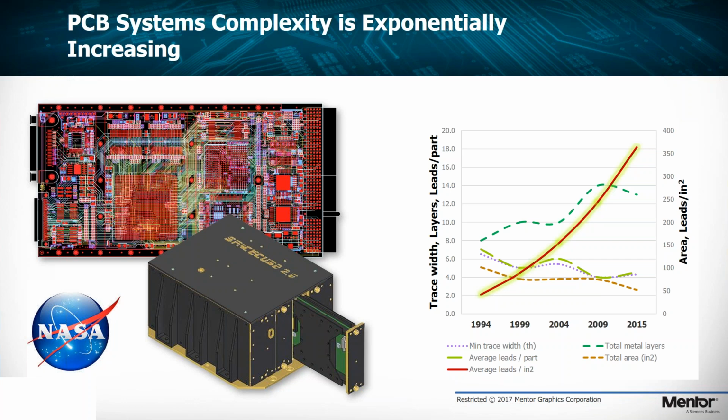So obviously Flex has some advantages. We can pack more on there, and have it in a smaller form factor, due to the fact that we are able to fold up the design and do some very interesting things with the board outline, not having a completely square or rigid form factor. And this board on the left is actually part of our Technology Leadership Award that Mentor does. It was designed in PADS, and it's just highlighting some advanced technology that you can use within some of Mentor's products. This is actually a NASA design that is used in this particular enclosure here.